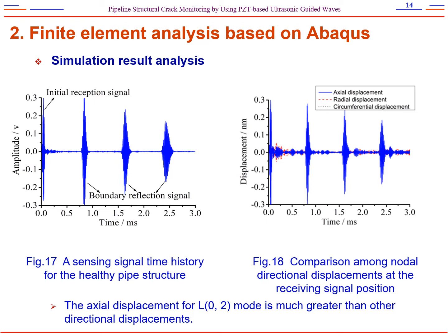Firstly, the axial, radial, and the circumferential displacement curves are extracted and compared, as shown in Figures 17 and 18. Figure 18 shows the actual displacement amplitudes of the signal package at the same nodes in the pipe mode are greater than the other 2 direction ones, which indicates that the displacement distribution approximately complies with the L-mode guided wave.